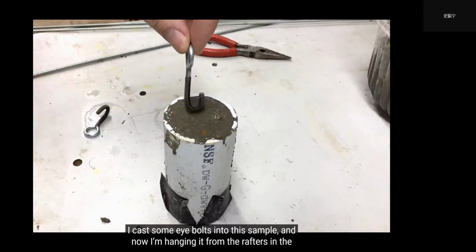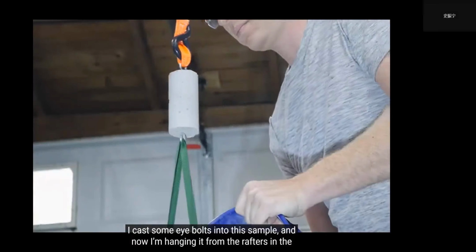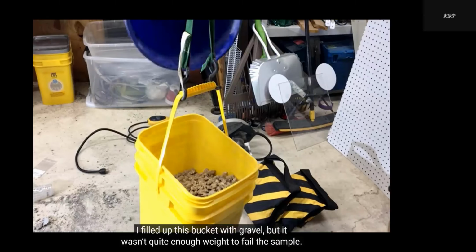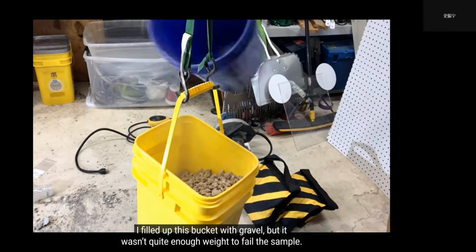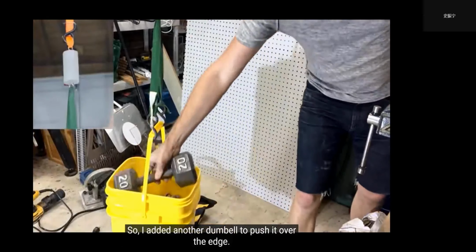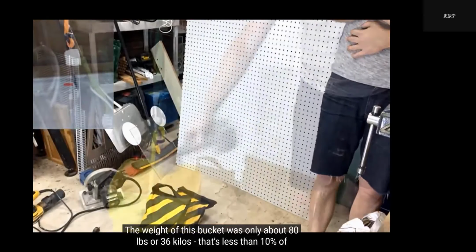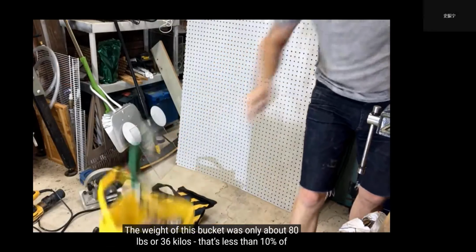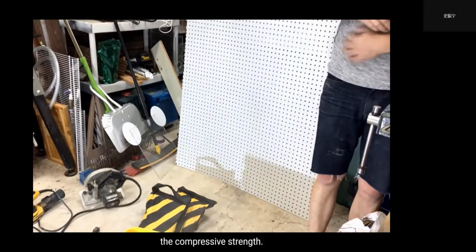I cast some eye bolts into the sample, and now I'm hanging it from the rafters in the shop. I filled up this bucket with gravel, but it wasn't quite enough weight to fail the sample, so I added another dumbbell to push it over the edge. The weight of this bucket was only about 80 pounds, or 36 kilos. That's less than 10% of the compressive strength.